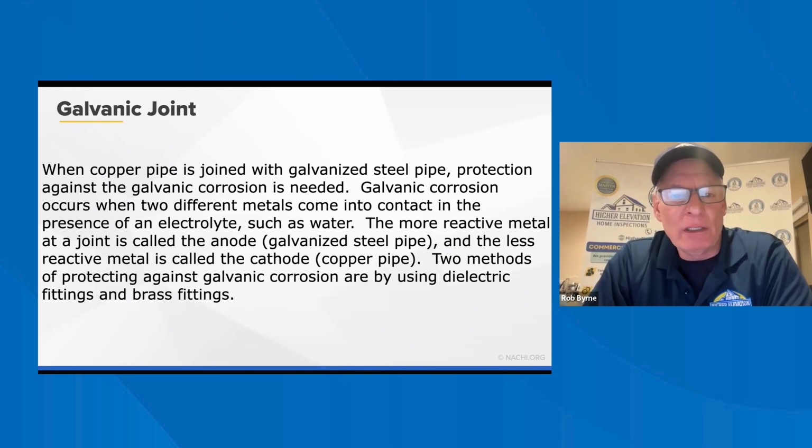I've heard people trying to turn the valves and they snap, and it's just a nightmare. And remember, they're going to be 50, 60 years old, so you're not going to want to play around with them. All the new plumbing, they use ball valves now. So that's important to call out when you're inspecting the water supply on the plumbing line. Look for these valves and identify the water main shutoff for your clients so they know exactly where to look for the valve if they ever had to shut it off immediately.